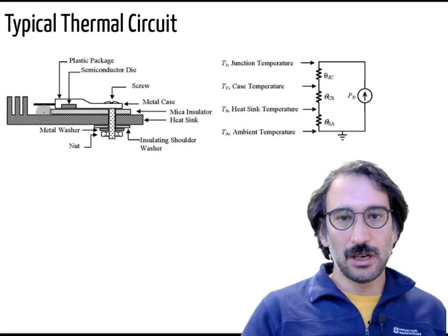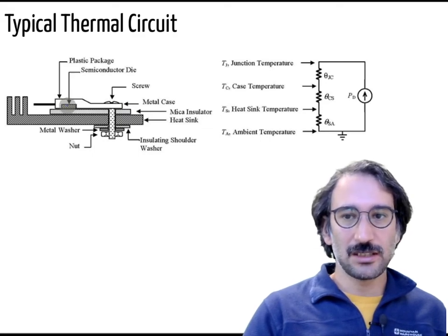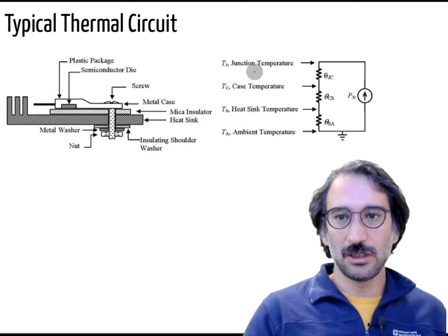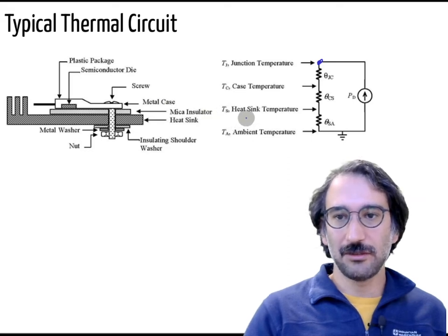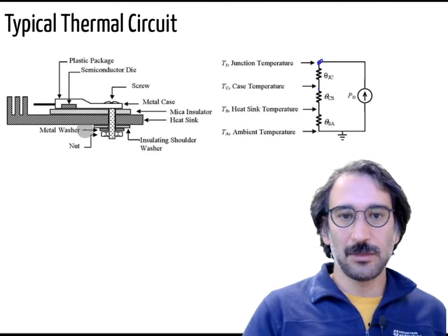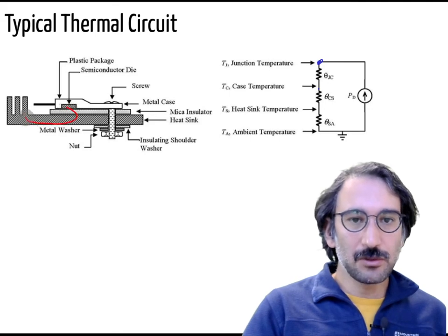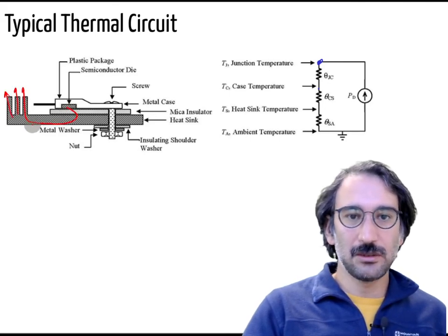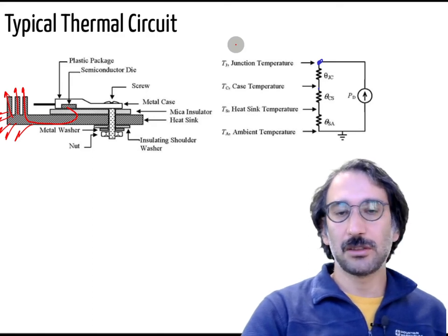You have a semiconductor here. This is just the packaging, but the actual semiconductor action, the PN junction, is just inside that one. So it is usually shown by the junction temperature, and junction temperature is most of the time the limiting factor. Then you have junction to case, case to heatsink, heatsink to ambient, and the heat is transferred, let me use the red, from here to the ambient, and you can estimate the equivalent thermal resistance and what will be the operating temperature of your power electronic circuits.